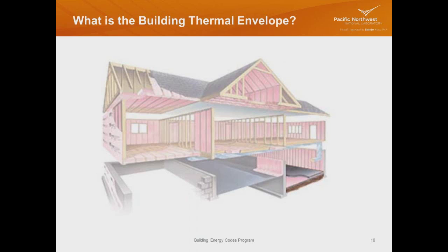And I'll show you more pictures as we get down further. It's not interior walls that are between 2 conditioned spaces. It's only the exterior building thermal envelope that defines the conditioned space. So if you have a 2-story building that's conditioned, you wouldn't show that interior floor between those 2 conditioned spaces. You would only have 1 floor, the bottom floor. Maybe that's your basement, or you have a walkout basement, so it's your slab on grade.